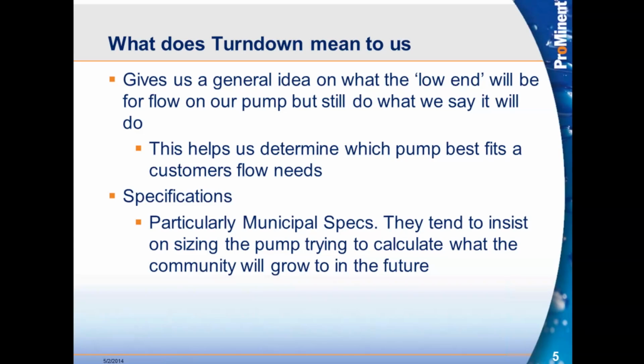So in that case, that means they're going to have to dose 4 times as much chemical in 10 years than they do today to treat that 4 times the amount of water. So they'll size that pump when they're building that water treatment facility to anticipate growth in a community. So that's why they'll specify a turndown to size the pump in.